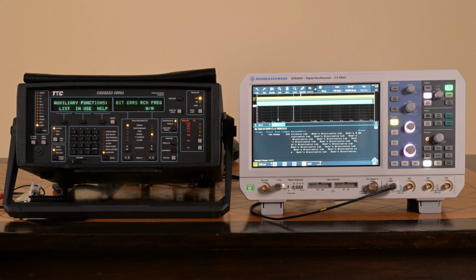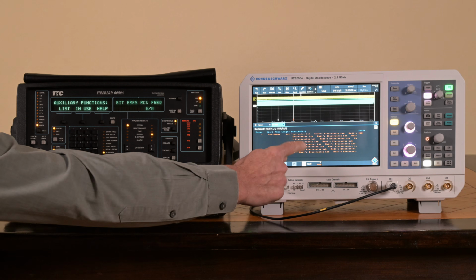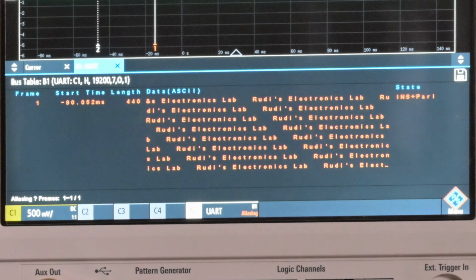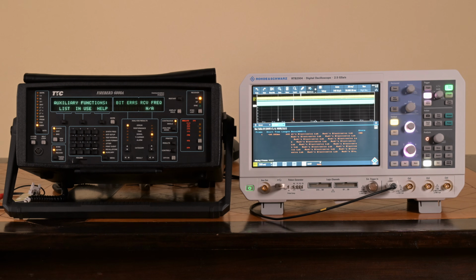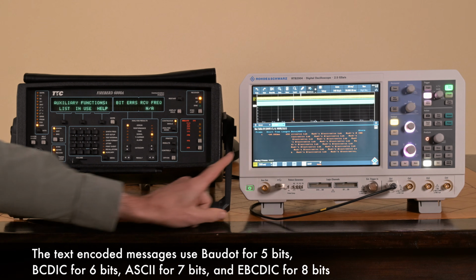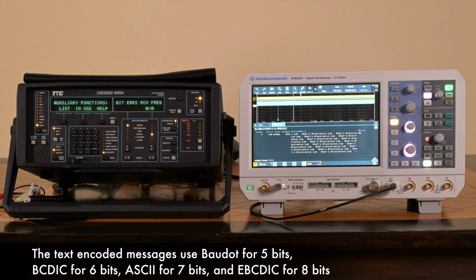And if we do that, then we actually get to see, I hope you can see it, Moody's Electronics Lab. So you can have predefined messages that you program into the unit. Actually, you have to do it by entering the hexadecimal values. You have to do it in 7 bits, by the way. That's the way it is defined, and you have to set your scope to 7 bits in this mode as well. It can also do 8 bits, but then it uses another alphabet than the ASCII alphabet, which is a bit interesting. But if you want to use the ASCII alphabet that the oscilloscope can decode, then you must use the 7-bit setting here.